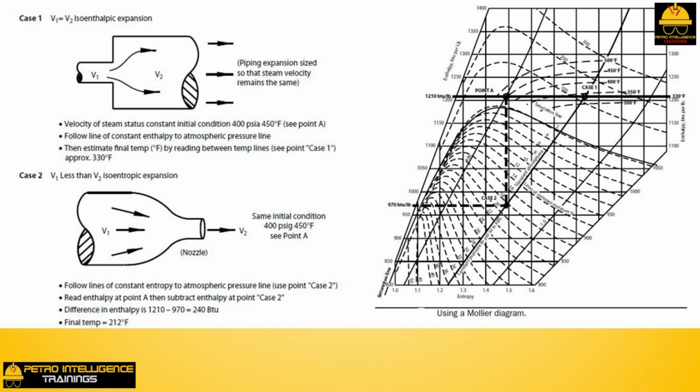Note that the numerical values expressed here are for illustration only. They are not correct in an absolute sense. You may study these concepts and arrive at accurate conversion rates of steam enthalpy to kinetic energy by using the Mollier diagram in your steam tables. Just follow the vertical isoentropic lines down the chart from the motive steam conditions down to the exhaust steam conditions.